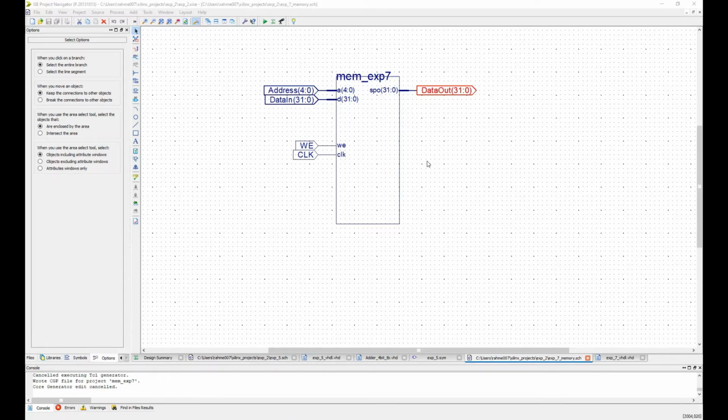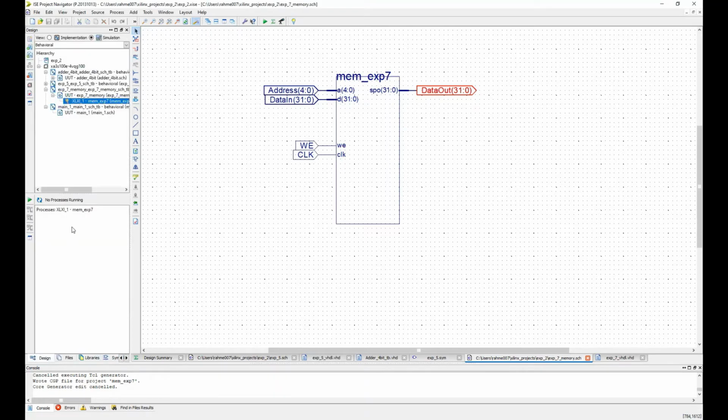After assigning these 4 input and output ports, as you can see in here, you need to go ahead and put the design option in here. As you can see, I put the design option, so you can simulate the behavioral model and see what's going on with the timing diagram. Also you can check it with the VHDL Testbench code. I'm going to go ahead with the VHDL test code, and for that, you know how to generate it from the previous labs, so I'm not going to go over that one.